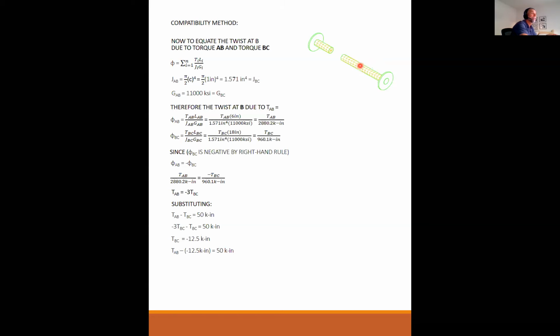But if I had added up A to B, which was positive, and then I added a little bit of segment here, which is negative, that total would be the relative twist here from A. And if I had done the exact same thing from here to C, it would have been the negative of the same answer. So yes. However far you twisted from A, you have to get back to 0 at C because A and C are both equal to 0.